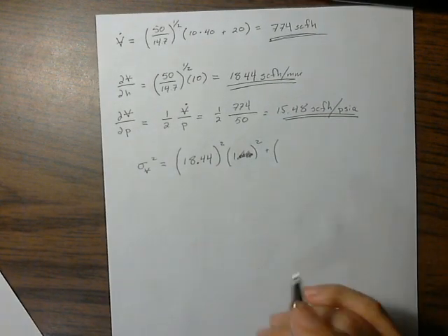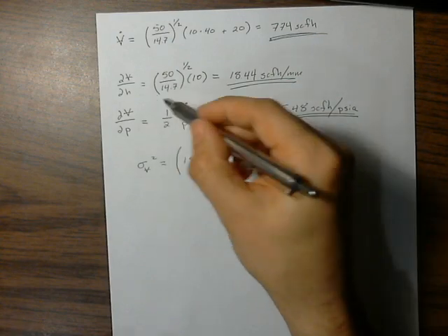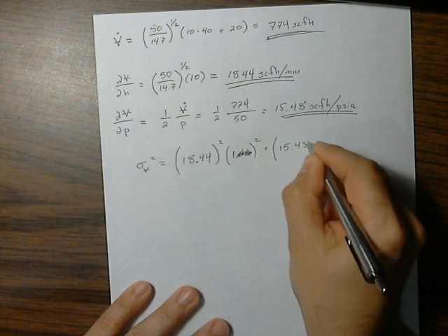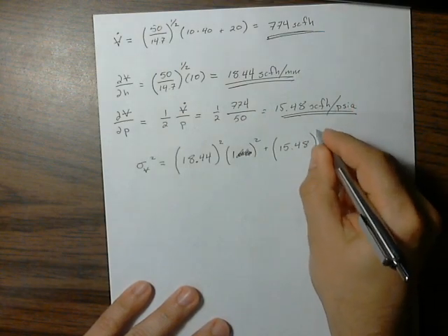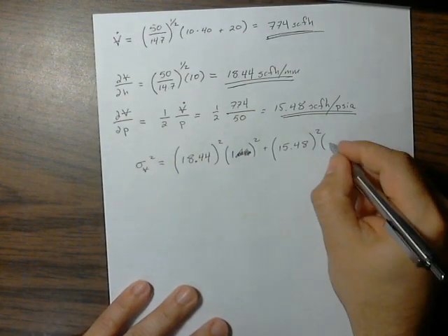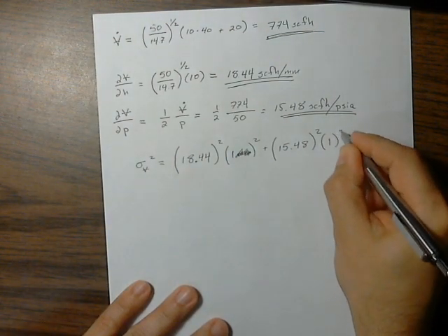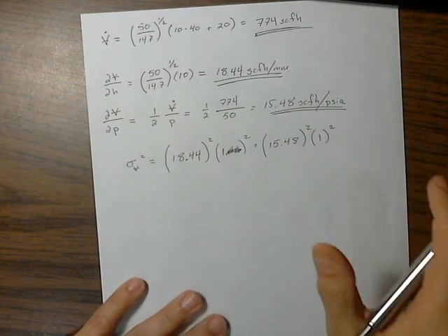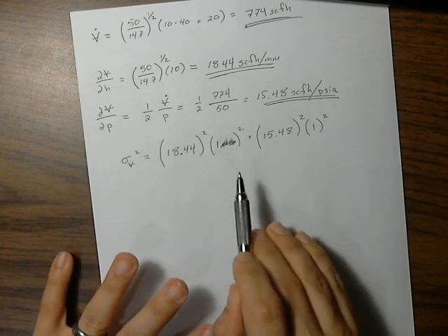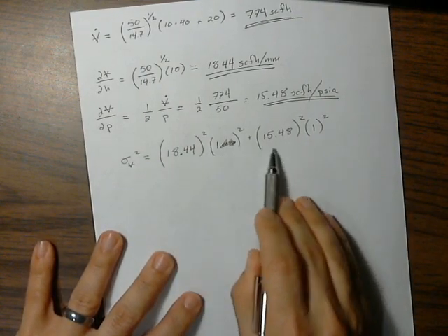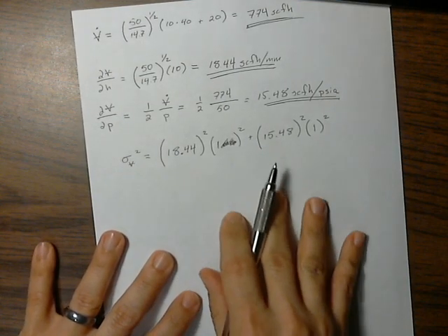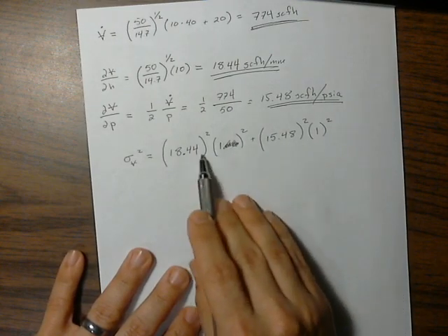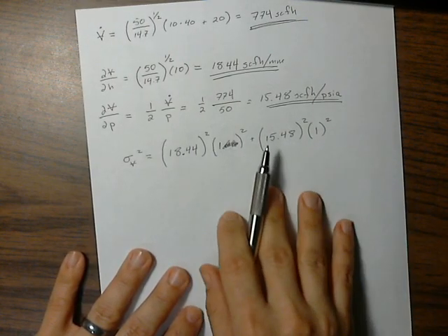And then we needed the partial derivative of V with respect to P, which was 15.48, excuse me. And then we said this was about 1 psi. So purely just by bad choosing of numbers, both of these are 1. The interesting thing about this analysis is it enables us to see where most of our error comes from. This is a really unusual case where just by the luck of the numbers, neither of these really dominates. These are both on about the same order of magnitude.